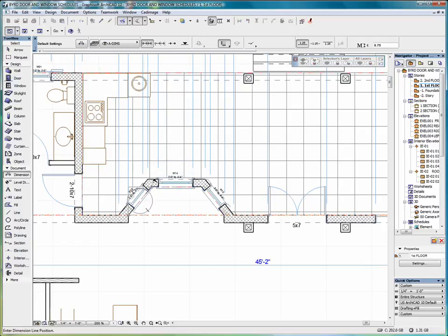if we place a node on an angled wall, we will still only be able to place our dimensions in a vertical or horizontal mode. The any direction method enables us to create dimension chains at a variety of positions relative to the element's position, either parallel to the first 2 reference points placed, or horizontal vertical, or parallel to another edge surface of our choice.